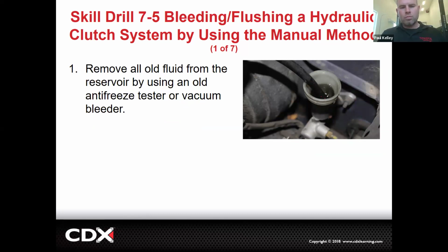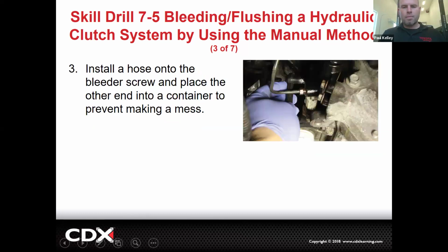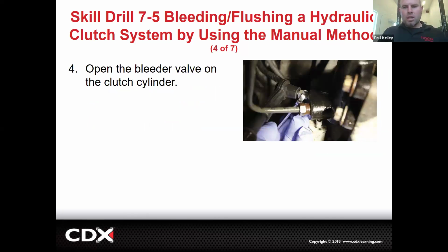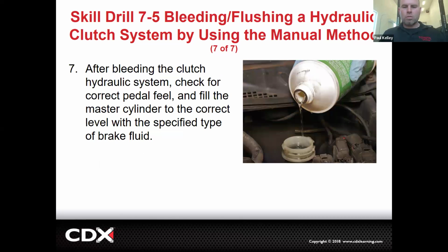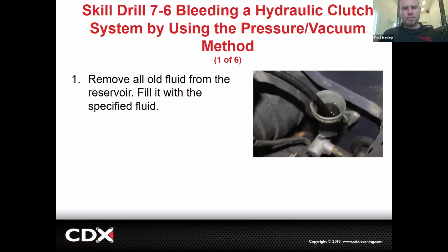And then if it's going to be just manual old school, you're going to literally suck out the old dirty fluid, fill the fluid level, just like last time. And then you're going to say, hey, Tony, jump up in there. Press the pedal down. You holding down? Yeah, it's down. Crack the bleeder. The pedal will probably loosen up just a little bit, but it's not going to go down because it's already down. Make sense? Close the bleeder. Hey, let the pedal up. Press it down again. While you're holding it down? Yeah, I'm holding it down here. Crack the bleeder loose, right? Just like manual bleeding of brakes. That's it. And then set the level.